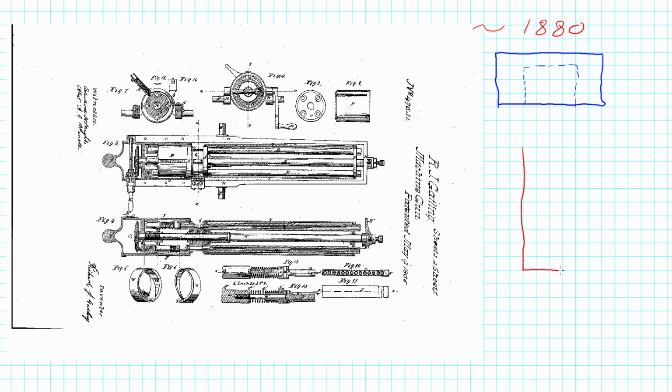Maybe this is a barrel, and it's kind of a short barrel, but you get the idea. Of course, we would like to have the barrel be able to fit into this end piece. To make sure that every barrel fits into every end piece, so we don't have to select them individually and fit them, we start to use dimensional tolerances.